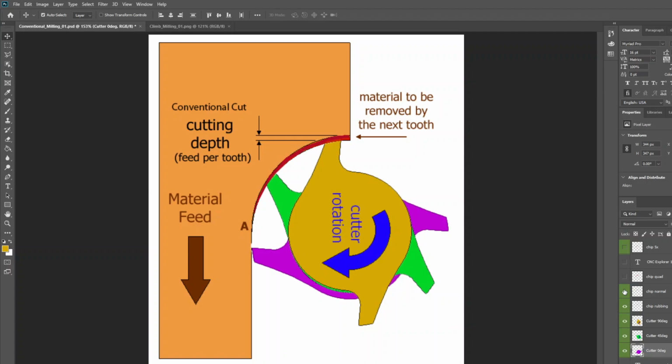So I'm probably going to make another video down the road talking about chatter. And this video, I hope it explained a little bit about the relationship between your feed rate and the width of cut. I don't think that's normally understood, and why it's really important to make your ratio between the RPM of your spindle and the rate you're feeding through your material be in balance so that you can make a proper cut.